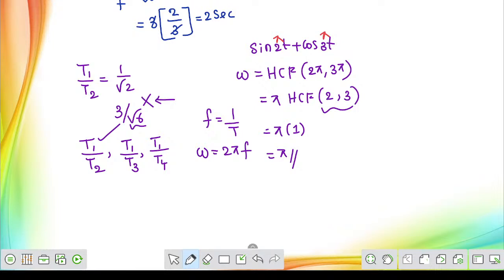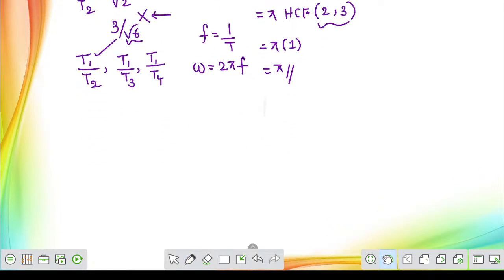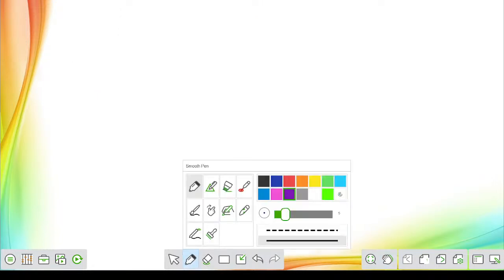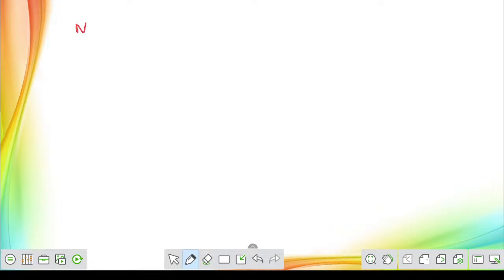So the periodic signal process is very important, continuously asked in the examination. Hope you all know this. So this is in the continuous domain. Same way, you can also calculate the fundamental time period in the discrete domain. Same formula. If they are asking the fundamental time period in the discrete domain, use the same formula, 2 pi by omega. But along with that, use some integer. So what you are trying to say?